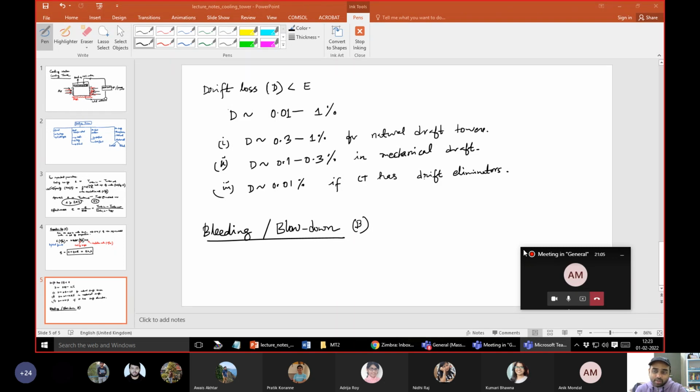But if the scaling is excessive, then at some point of time it will degrade the equipments also, right? After some time there will be huge loss of the equipments. So cleaning to some extent does help in reducing the fouling or the scaling, but ultimately this will also reduce the lifetime of the equipments, right? And in a continuous plant, whenever you want to do cleaning, you have to shut it down. So there is also an economic loss due to the interruption in productivity.